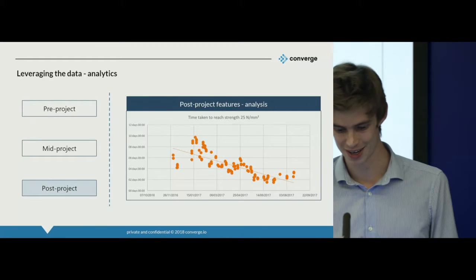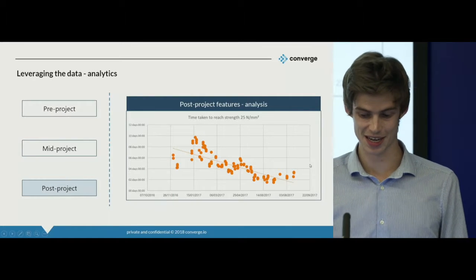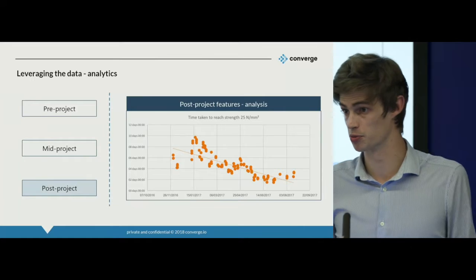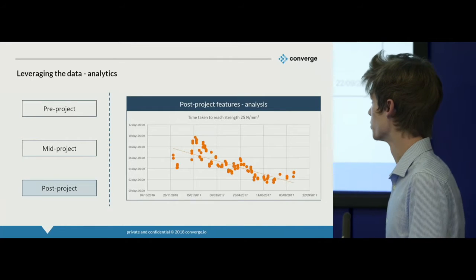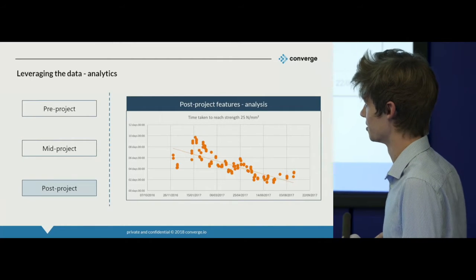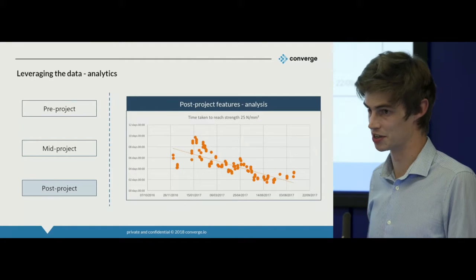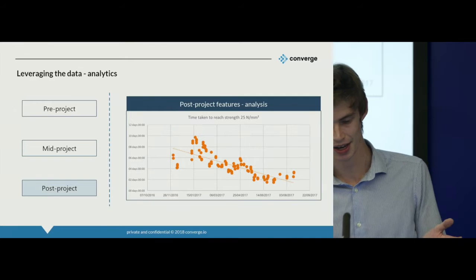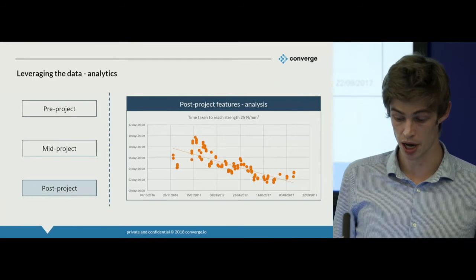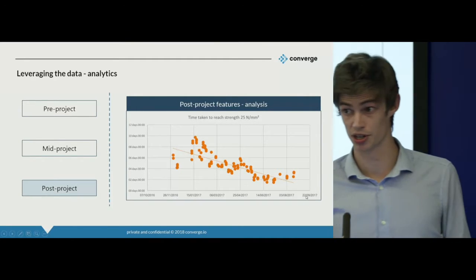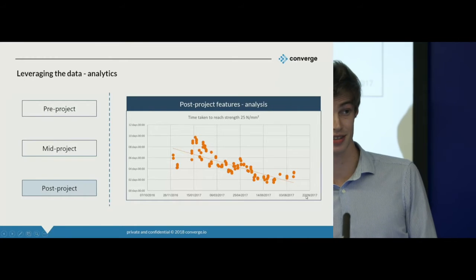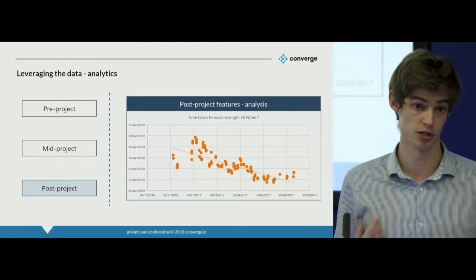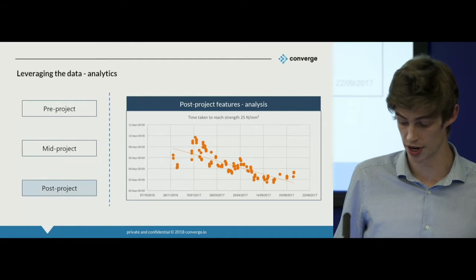Just to reiterate, all through the year, they're seeing exactly the same flat performance with no real impression of how that concrete is performing through the year. So using this data, they can start to infer, perhaps I should be leaving a few days extra in December through January to account for that slowdown. But as I get into the summer, perhaps I can leverage those gains and build this into my program and rely on faster strike times or tensioning at a faster rate.